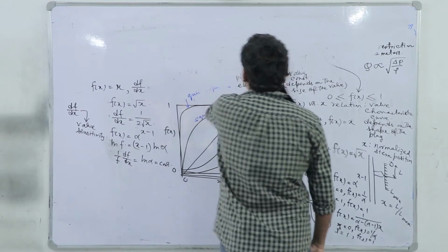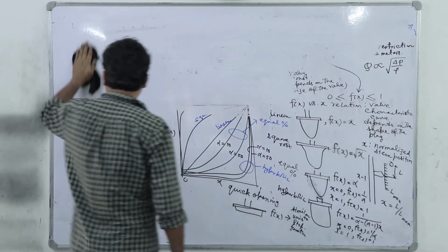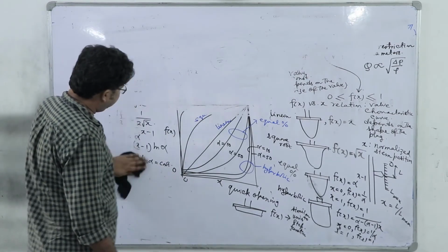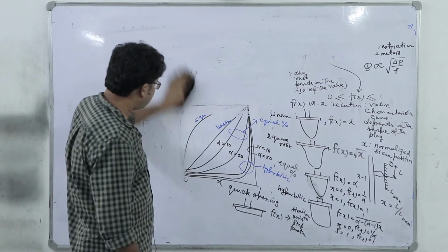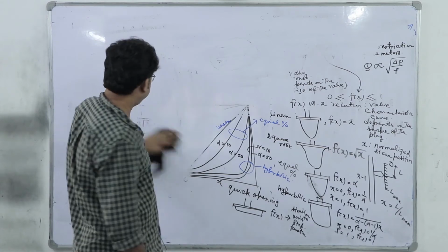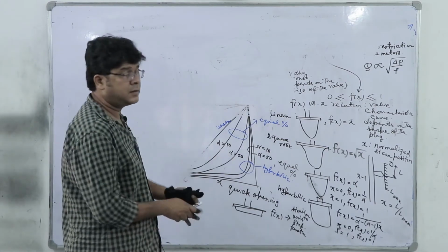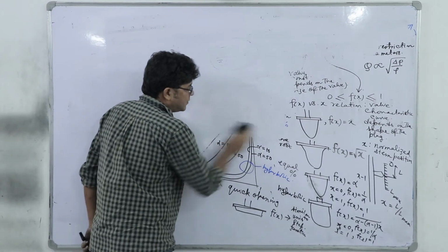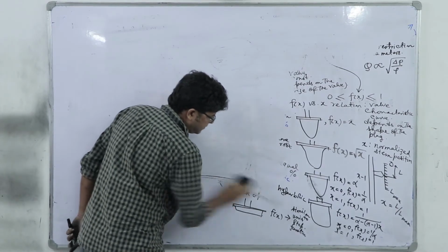Why is it a second order system? Because originally we modeled this F and X, it follows second order kinetics, and if the mass of the stem and the plug is negligible, it will follow first order kinetics, right? It will be overall first order kinetics because X and Q share a pure gain relation.